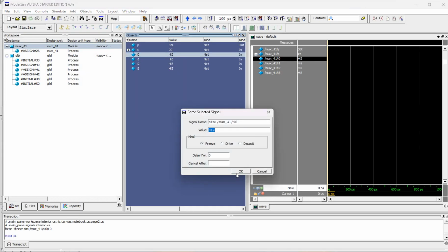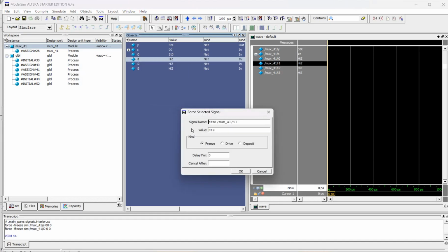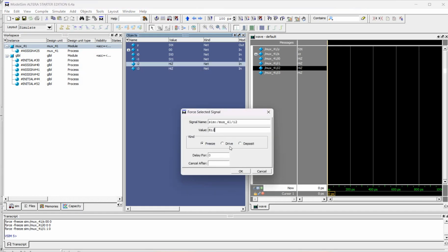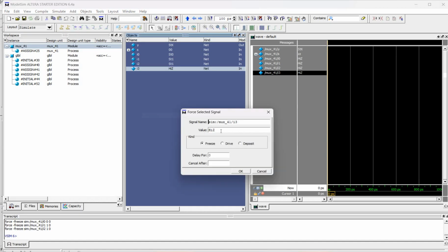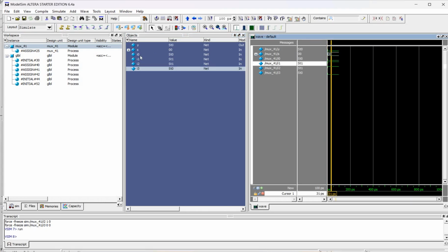I'm giving I0 as 0, I1 as 1, I2 as 1 and I3 as 0. So when we run the program, for S equal to 0 0, whatever is there in I0 will be the output. I0 is 0, so the output Y is 0.